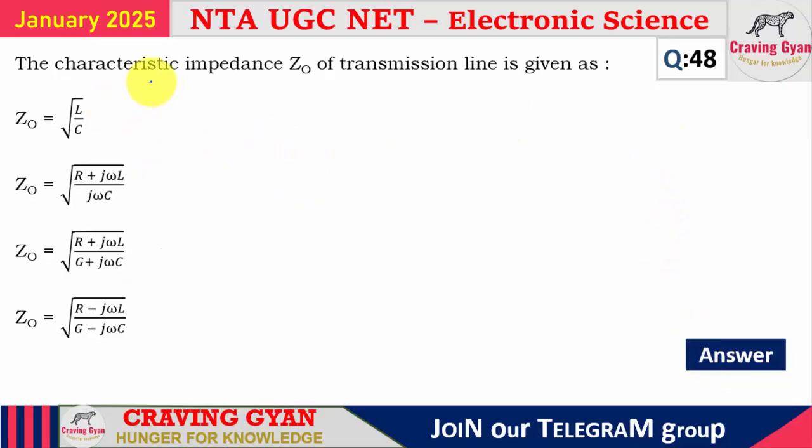48th question, the characteristic impedance Z0 of a transmission line is given by. See, in the case of a transmission line, they are given in terms of Z0, but in the case of waveguides, they are going to express it in terms of eta. Such a simple change, that's it. See, if you know waveguides, transmission line will be dead easy. Only the parameters you are going to change, that's it. Here you are going to represent it as Z0, there you are going to represent it as eta naught.